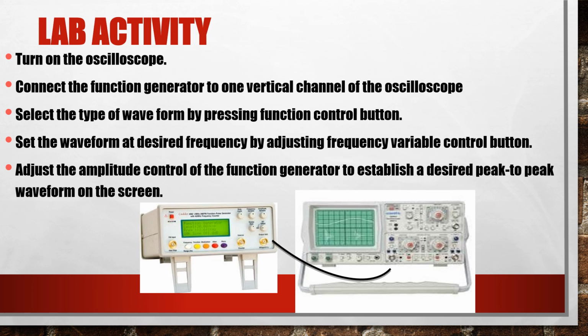Then adjust the amplitude control of the function generator to establish a desired peak-to-peak waveform on the screen of oscilloscope.